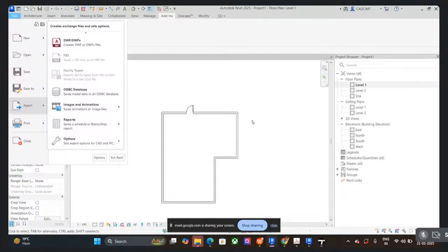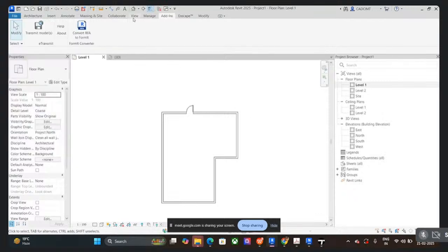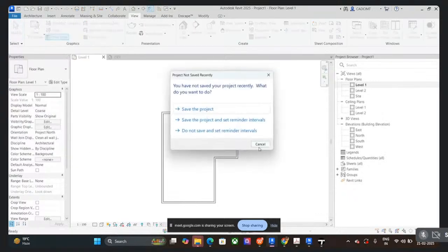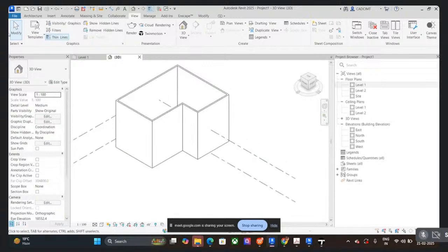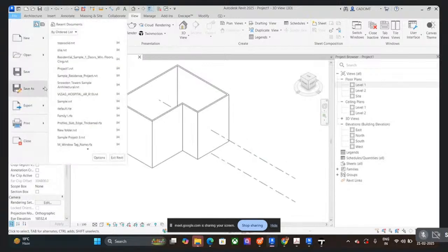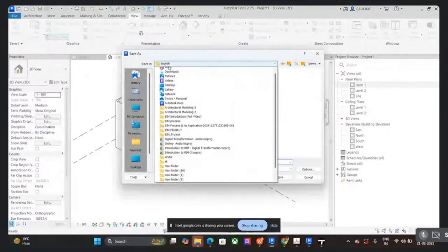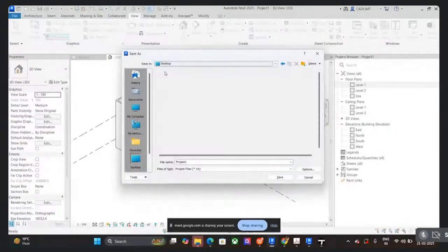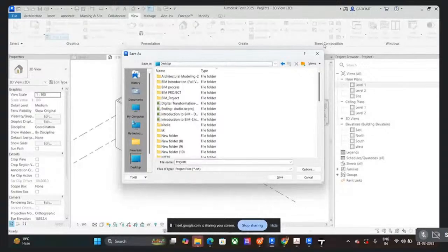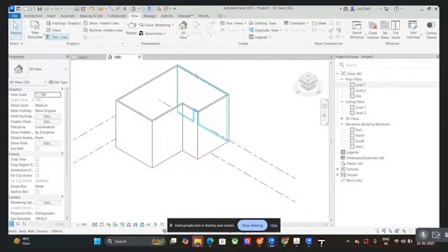But what you can do is directly open a Revit file, for example, in Navisworks. Now, let's say I have this model over here. And if I save this model, how do I open it in Navisworks? Let me give you a basic example, because I don't have an NWC exporter currently, but you need to have a plugin which is called an NWC exporter.